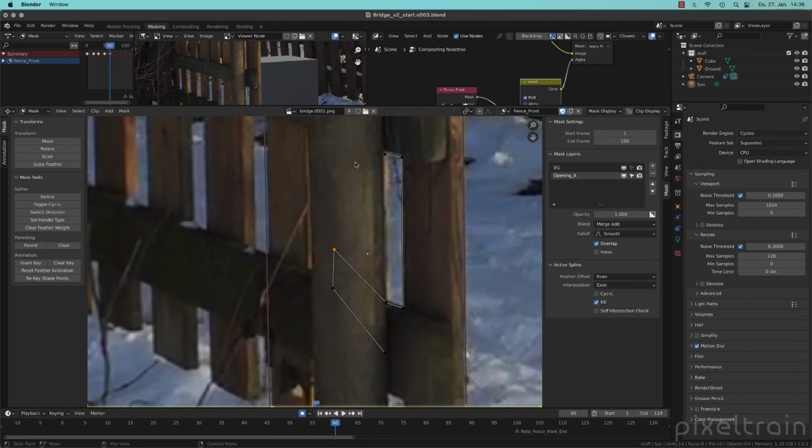I don't need that here. This was only an experiment, so I select all the points and remove them. And now I go in here and make only 4 points. So I click, click, click, click without dragging. Alt-C to close that. Then I select all my points and say here vector. So now I only have vector points. And now I can start here adjusting these points.